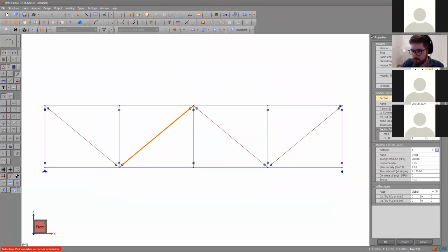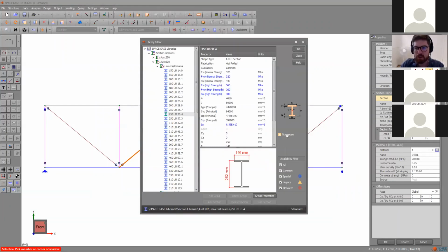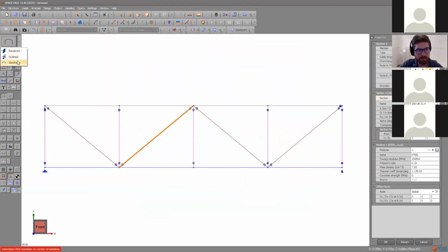So section properties, oh sorry, one final note on section properties, this button here. You spent a good 2 weeks of your structures education looking at major and minor principal axes, and then that wasn't closely looked at for the rest of the course, but you need to control which way your section is being oriented.